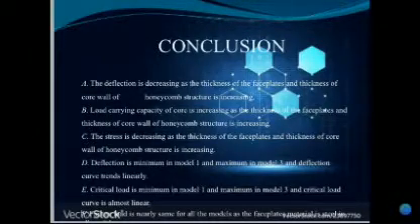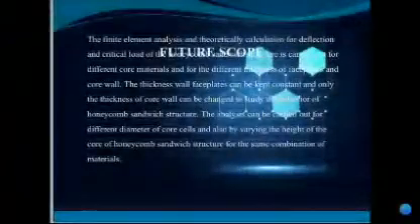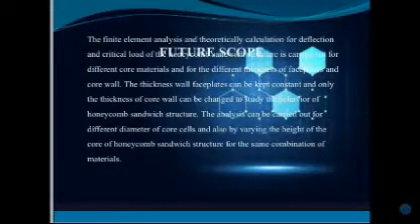Next, by this we will conclude that the deflection is decreasing as the thickness of the faceplate and thickness of the core wall of the honeycomb structure is increasing. Load carrying capacity of core is increasing as the thickness of faceplate and the thickness of core wall of honeycomb structure is increasing. The stress is decreasing as the thickness of faceplate and thickness of core walls of honeycomb structures are increasing. Next comes future scope.